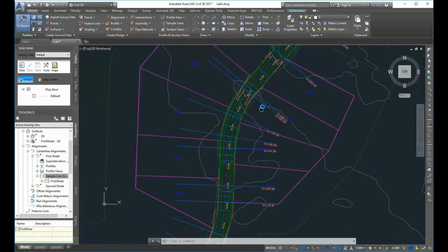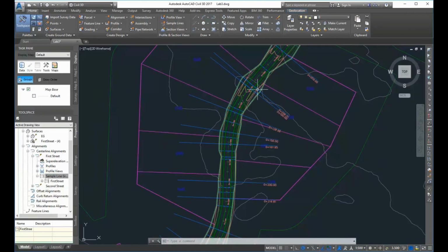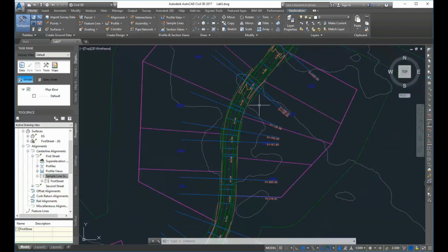But really what you're looking for is you want to make sure that you're capturing the daylight lines. So we'll talk a little bit more about that, but essentially you would have this is the point, remember, where your cut and your fill lines intersect with your existing ground, and if we're trying to calculate earthwork volumes, we need to at least look beyond that point, or else we're going to be missing significant amounts of earthwork.